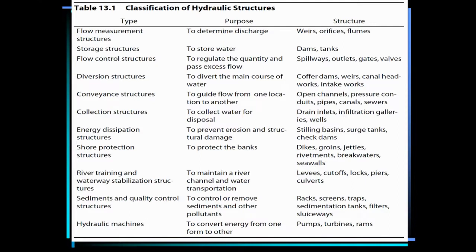Which are usually open reservoirs, depending on whether it is a huge pipeline like a penstock. A penstock is a large diameter pipeline, like for hydropower generation. So in such a case, a water tower, in which we will avoid the occurrence of water hammer in the penstock.